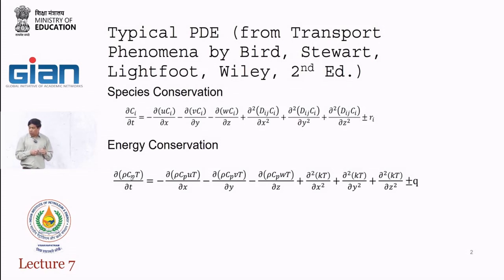Also, one thing that we'll keep discussing more and more is that one issue with the solid sorbent is that they are stagnant, right? There is a bed and they cannot move anywhere. So that's a problem with the solid sorbents: whatever temperature picks up, who takes away the heat? Only the flowing gas will take away some of the heat, but as we know, the specific heat of the gas is very small, so it cannot really take much heat. So it's only through the flow rate that you will get some heat out.